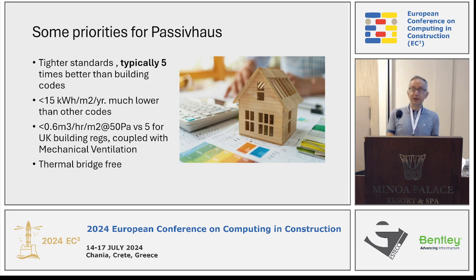I air pressure tested my house, which is a 1950s house, and it came to about 20. So with all this, you can see there's a lot of air movement, air leakage, and infiltration, which causes discomfort. Discomfort isn't always about having thick walls. It's about infiltration. It's about heat loss. To give you an idea what 0.6 air changes per hour is, the heat loss for the entire house can be the size of a €2 coin. That's how airtight these buildings are.